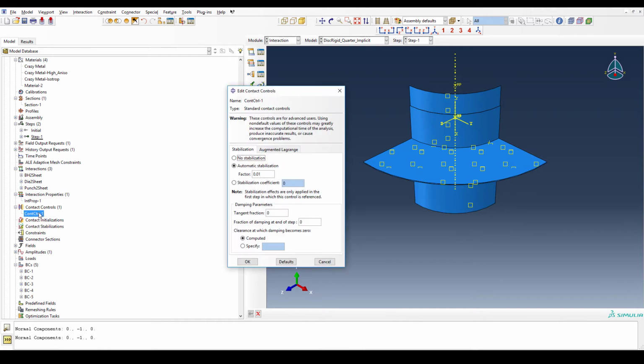window here. So contact control was another big thing that we talked about in the video, because especially if we do this in an implicit manner, right? So the people will just, because of the problems that the specific deep drawing operation poses in terms of numerical challenges, the people will just automatically go for explicit simulation and say, yeah, go, and I don't want to deal with it.